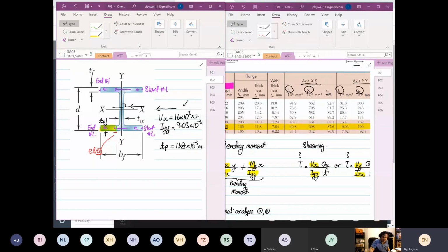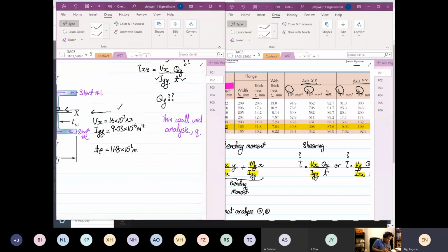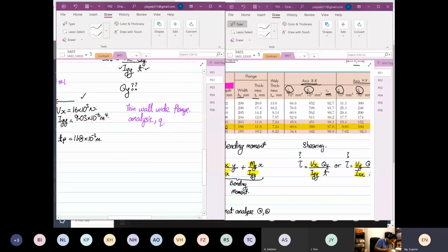Now this is multidisciplinary. Okay, that's where this is really useful stuff for all of us. When we have detailed analysis now, it's not just force divided by area, My over I. Now we have to combine all of them. So we have to find the first moment of area over there. Like what I said, I'm also a bit confused now. So we have to find QY.